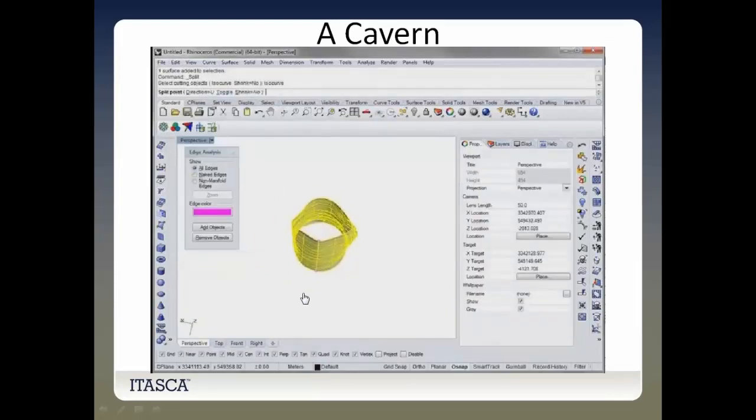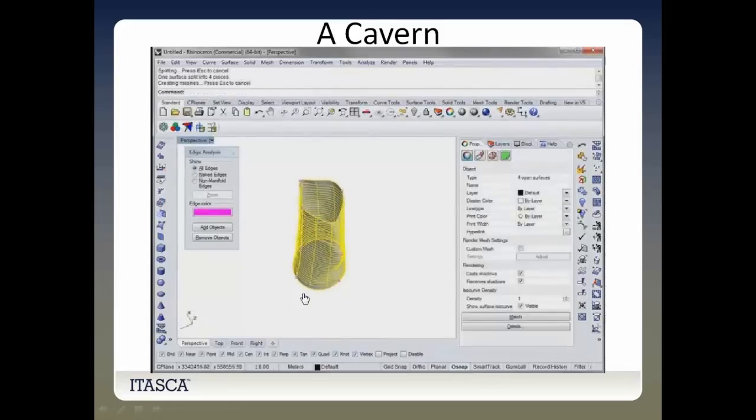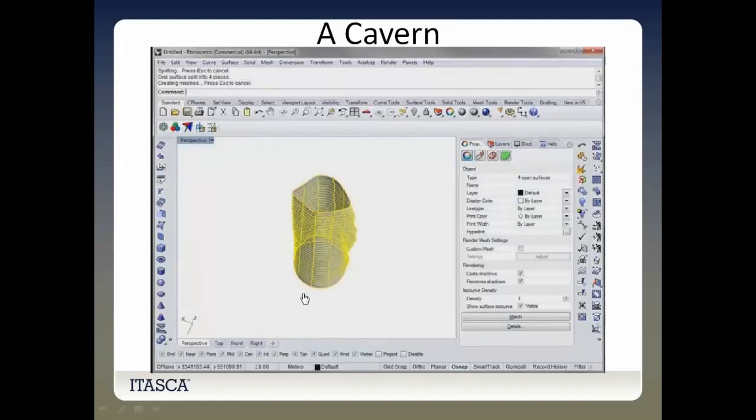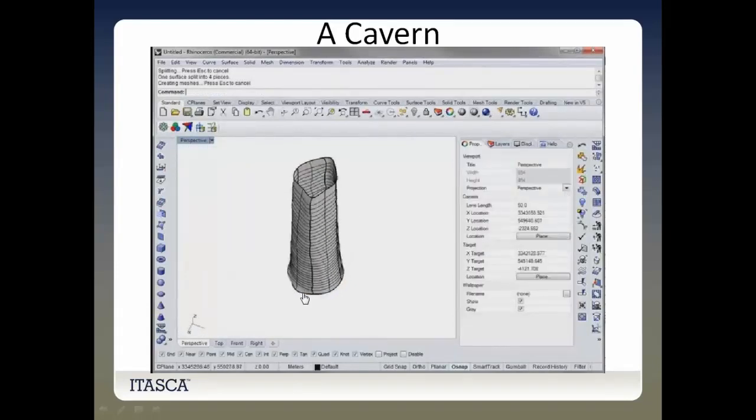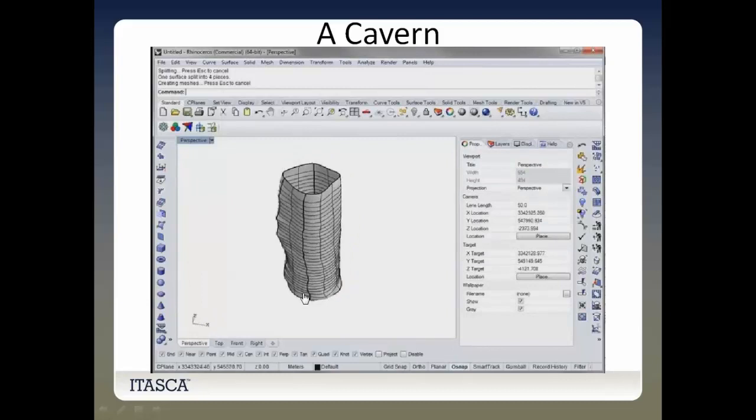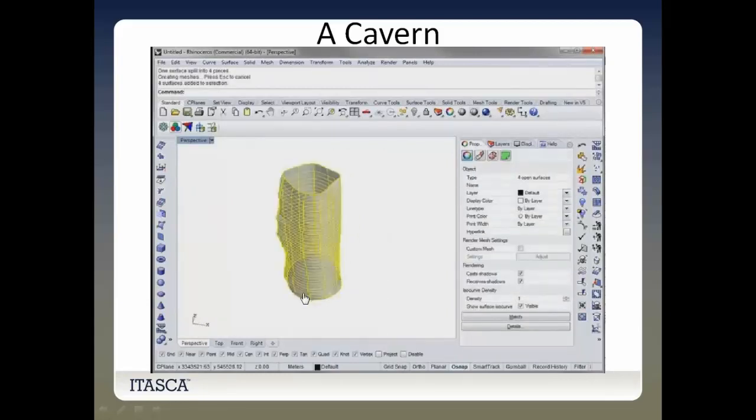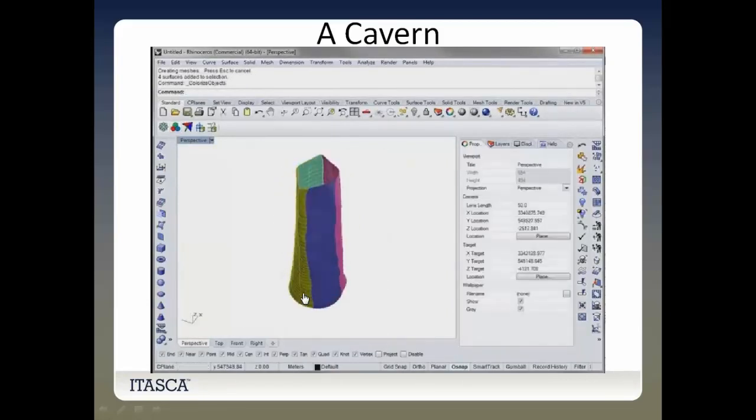So one of the seams. I'm going to split this solid, this surface here, along an opposite one, and then I need to put this cutting in certain areas so as not to produce very distorted zones. Because this is manual meshing, you have got to be careful where you cut your object. It's exactly the same sort of reflex you go through when you create this mesh either in FLAC3D using the Gen command, or using IconCFD, or using HyperMesh, or using FEMAP.